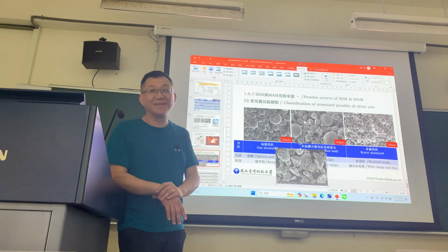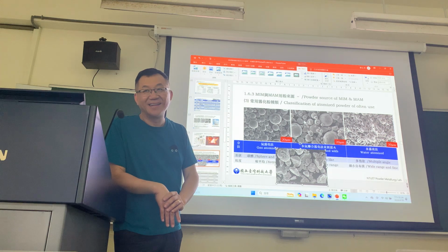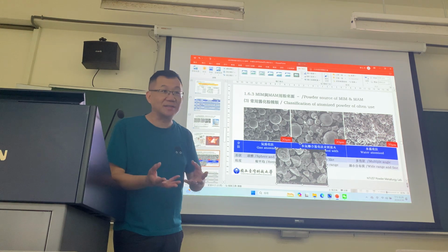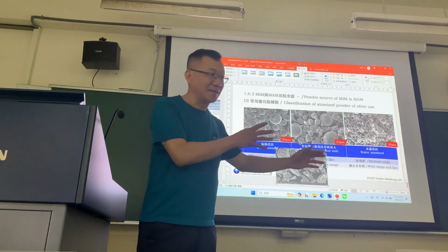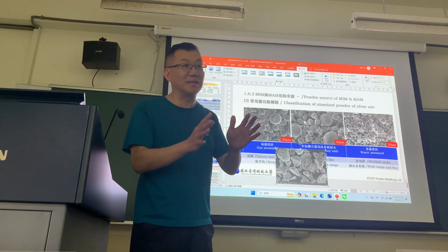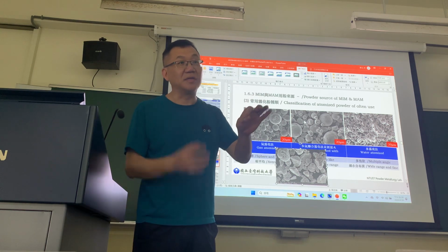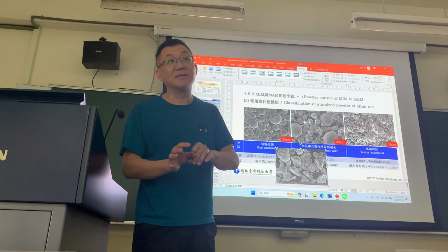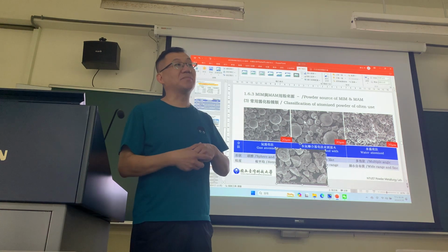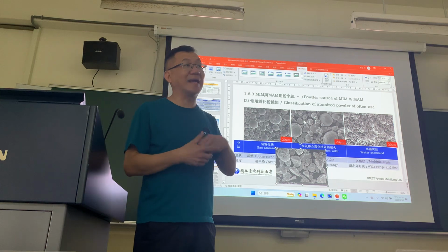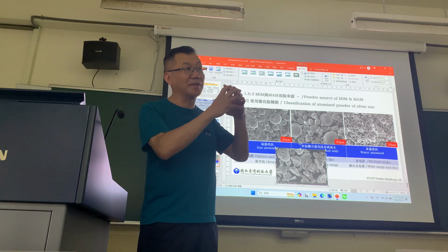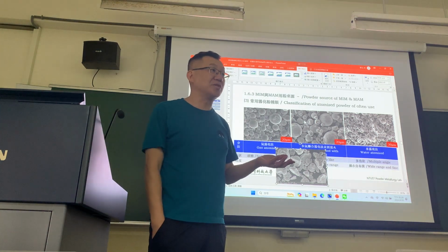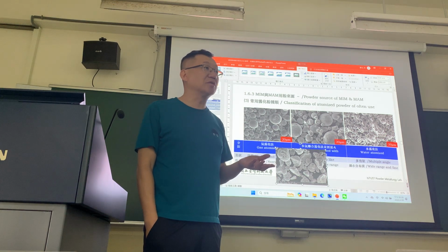Second one. Why? Because it's shaped. It's not natural. Yeah, it's by process. So every process you add money, and you need to buy raw material and make the powder become a ball. You need to control many parameters, for example the temperature, the gas pressure, and the gas. Because if you want a very good shape, you need to use nitrogen or argon for protection during the process.